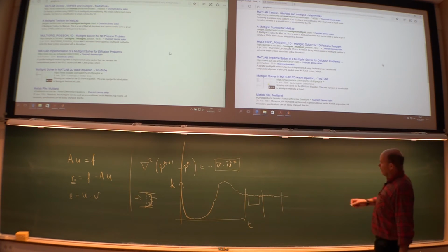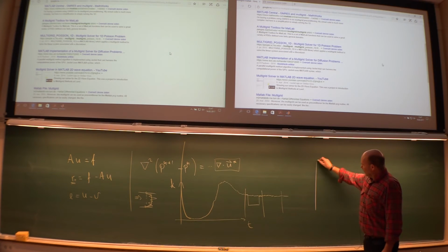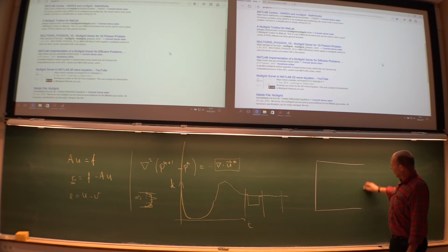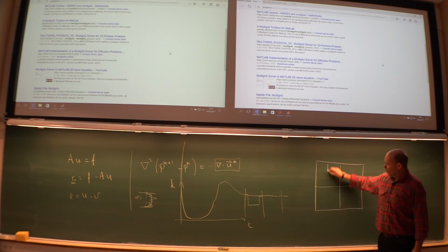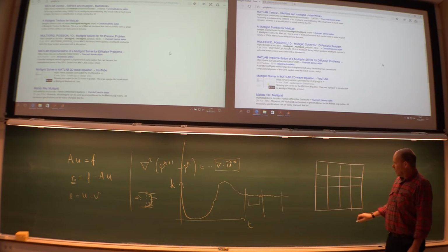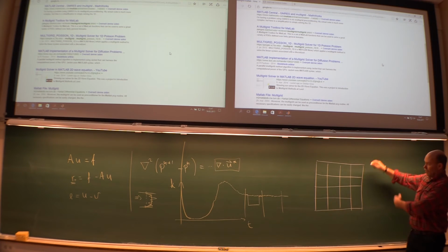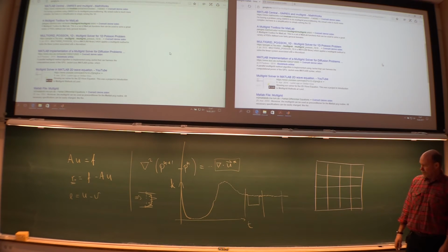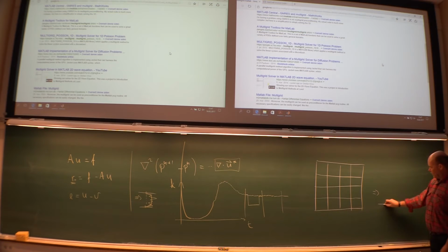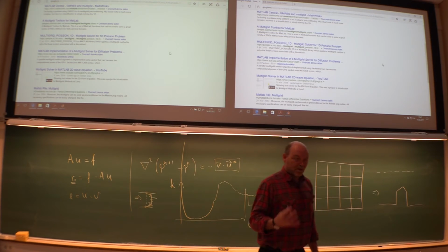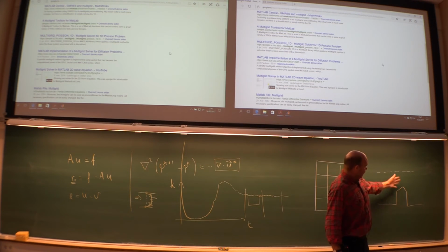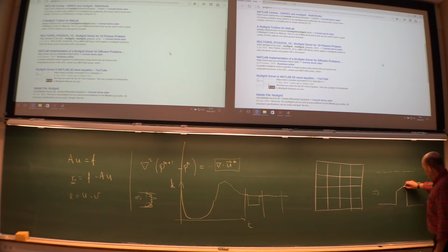When you have nasty geometry... if you have this nice rectangular area, no problem. Of course you can divide these into finer and finer meshes, and your coarsest mesh can be just one single big cell, beautifully, not a problem. But if you have a flow around a house, something like this, okay, simulate this one. That's not so easy. The coarsest mesh must still cover the geometry, so this will not be easy.